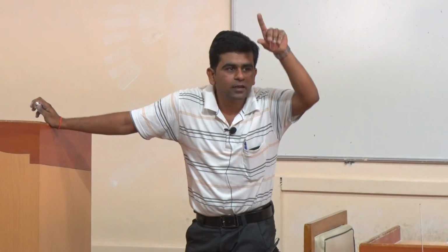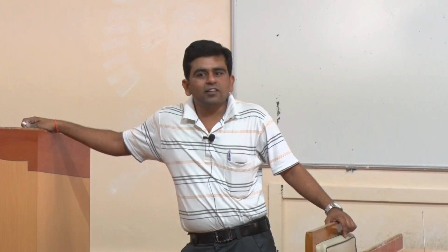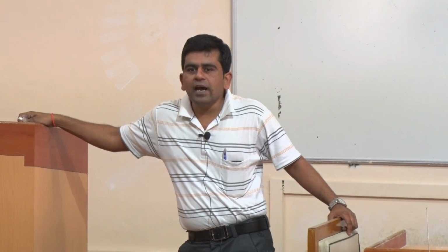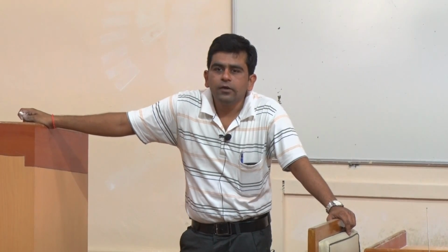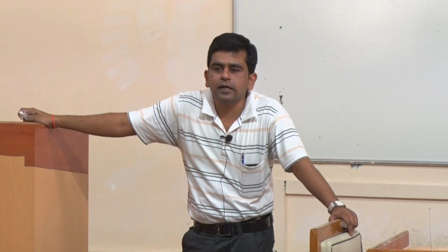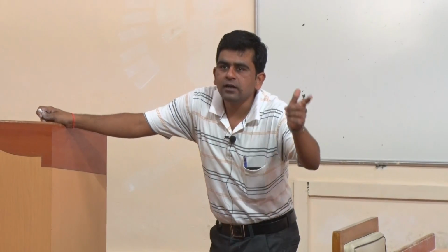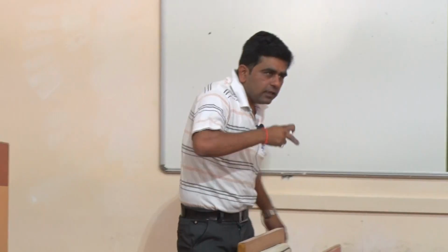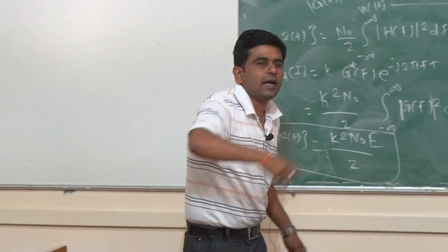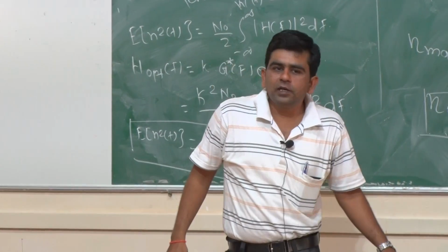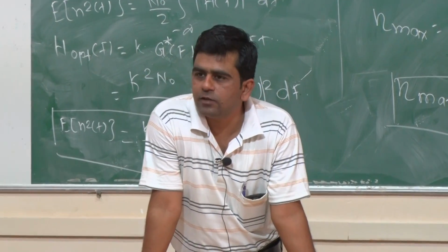We will get a line with some slope. When we are using the synchronous detector, yes, we are having the linear relation. When we are using the envelope detector, up to the threshold point, they are having the linear equation. After that, they are non-linear. So here in AM, bandwidth is the problem.